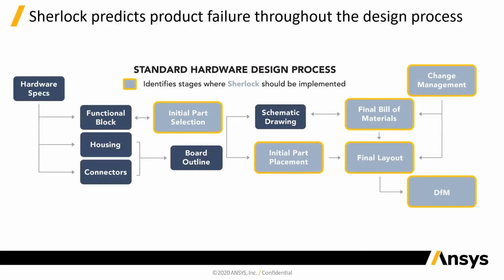Sherlock provides most value when implemented in the early design stages. So, for electronics engineers looking at the initial part selection for identified functional blocks, there'll be a handful of key components, and these can be input into Sherlock to run quick tests and work out any physical component mismatches. Essentially, this is running a quick coefficient of thermal expansion check on the components, providing a yes/no recommendation for suitability.